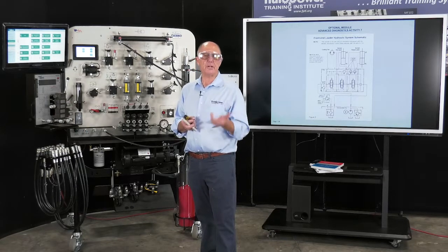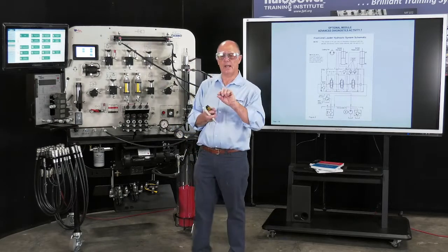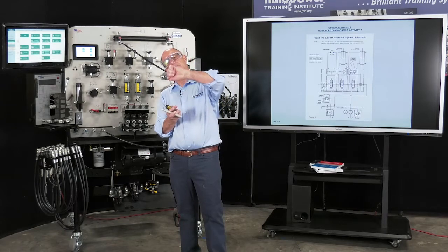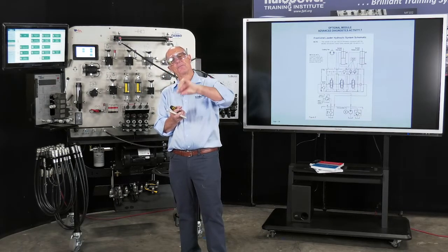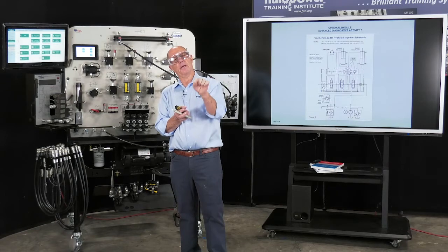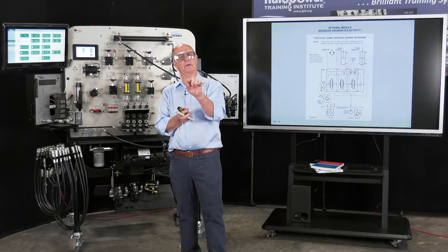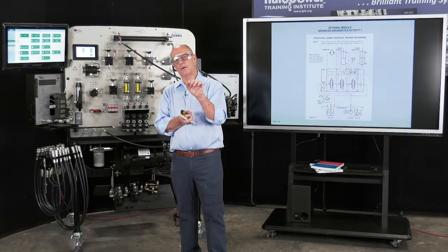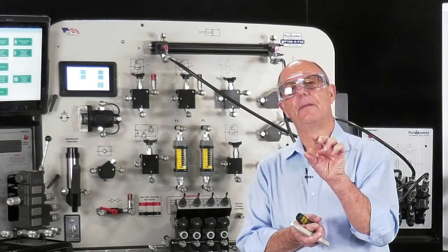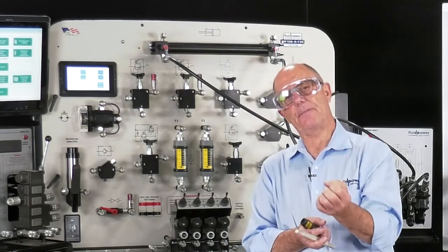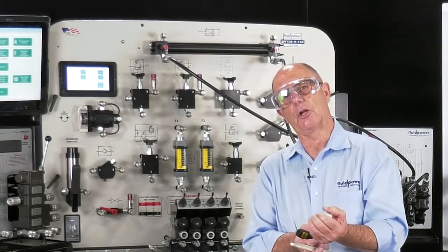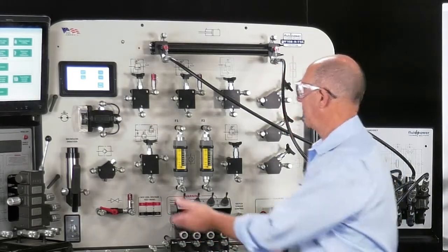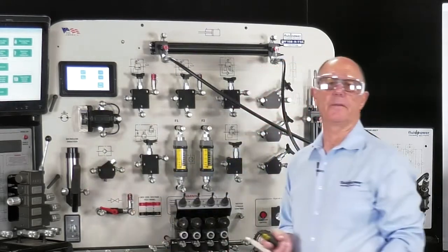When I originally started this research, I had test tubes and steel lines coming off the valves, and I turned them around into a test tube so I could actually see the leakage rate on new valves and valves that were terminal. And I learned what that sweet spot is. I also learned that I had to have a pump that produced a certain amount of volume per stroke in order for it to work. In other words, this is a Microleak test pump on the simulator.